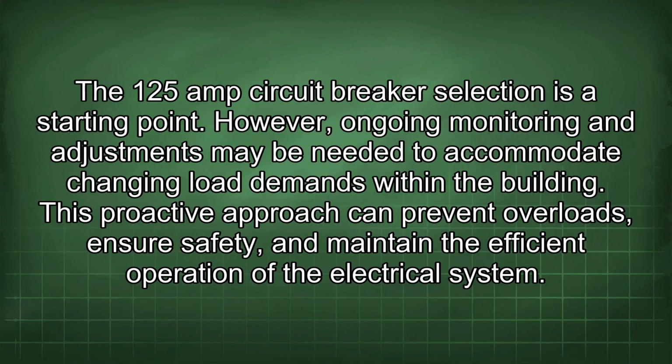The 125 amp circuit breaker selection is a starting point. However, ongoing monitoring and adjustments may be needed to accommodate changing load demands within the building. This proactive approach can prevent overloads, ensure safety, and maintain the efficient operation of the electrical system.